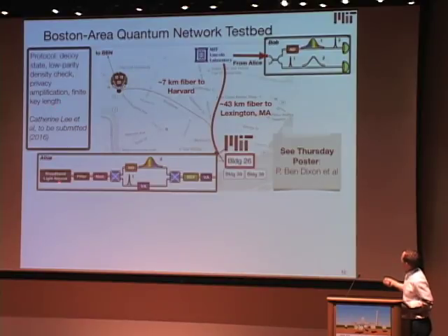And it consists of a broadband light source that's filtered, modulated for pulse carving, and then sent either deterministically to a normal group velocity dispersion element, which spreads this photon out in frequency, and sends it to Bob, or it sends it in the other basis directly over to Bob, who then measures randomly in one of two possible bases, either using anomalous dispersion that rephases this wave packet to a given temporal mode, or in direct detection.